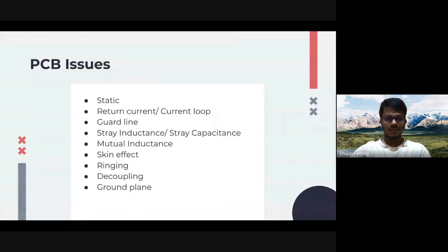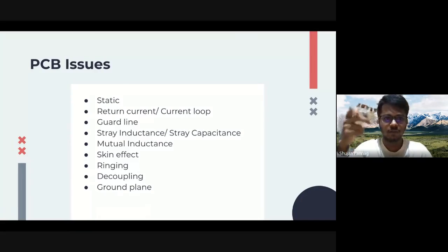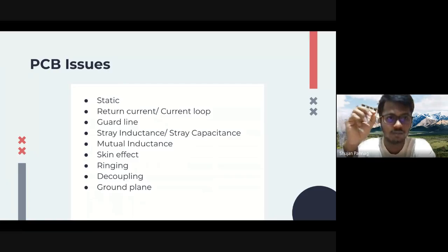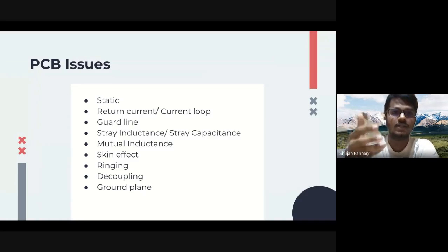That's great. So skin effect is really important, and it's an issue in PCBs. The copper tracks are really thin. So when you have high frequency or any sinusoidal components running through it, due to skin effect, the current flows only in the surface area. So the cross section of the copper track, even though it's there, doesn't get used up fully. Now if you go through the resistance formula, the surface area decreases, so your impedance increases. So you're effectively increasing the impedance in your circuit, which is really bad, because in high sensitive and high precision circuits, it's a bad thing.